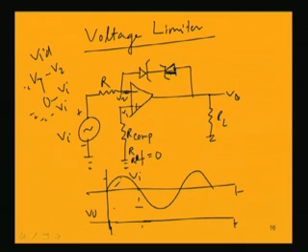This will not be the saturation voltage, because as this Zener diode is connected, what will happen is that when it is negative, this diode is say D1, this diode is say D2. So, the reverse breakdown will be taking place in the case of the diode D2, because it is connected in the reverse direction, and as far as the diode D1 is concerned, it will have the ordinary drop of around 0.7 volt, that is typical for silicon.